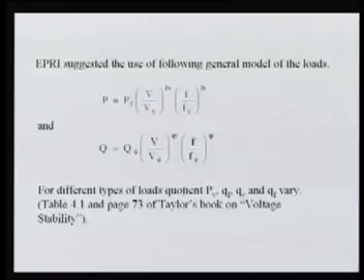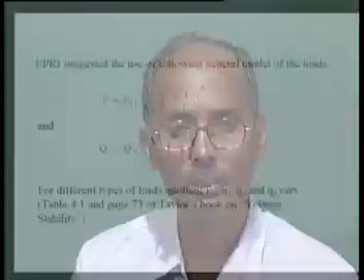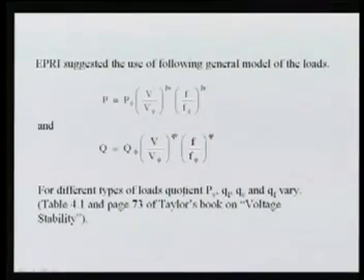Now again there are several methods and several books and references that have suggested models, like EPRI of USA suggested the use of the following general model of the load, and they have used P is nothing but your P naught, now multiplied by V divided by V naught. Here V naught is your nominal voltage, here it is a frequency, nominal frequency, and what is your system frequency.